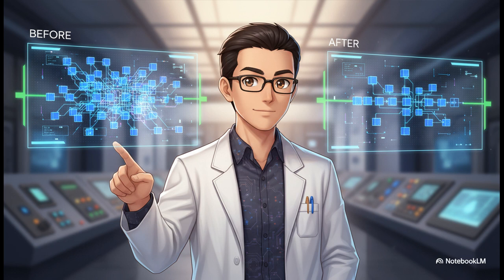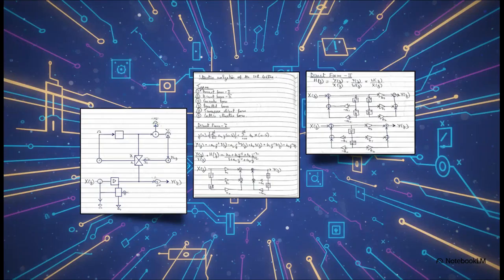Those things are a crucial resource, so using fewer of them, well, that's a huge win. And check this out. Here they are, side by side. On the left, our first draft, Direct Form 1. On the right, the optimized Direct Form 2. They both do the exact same thing mathematically, but if you look close, you'll see that Direct Form 2 is super clever. It combines the delay elements into one central chain, basically cutting the number of memory blocks in half. Same result, fewer components. Now that is just smart design.